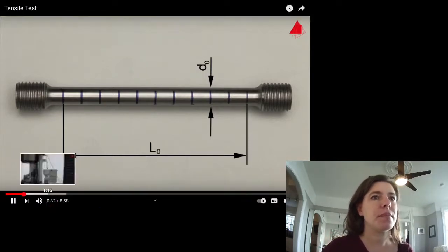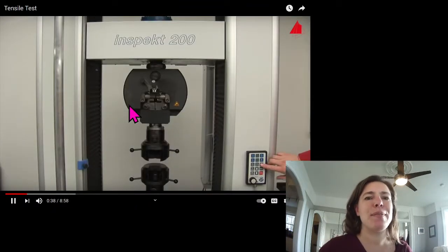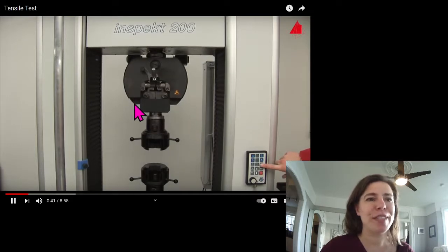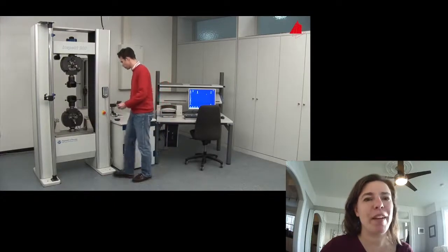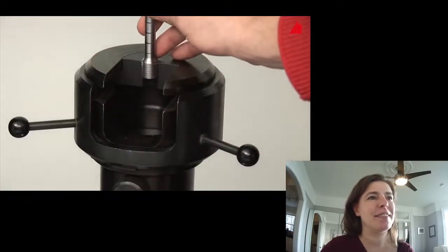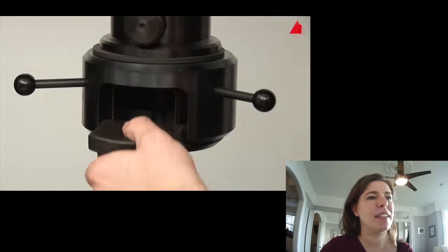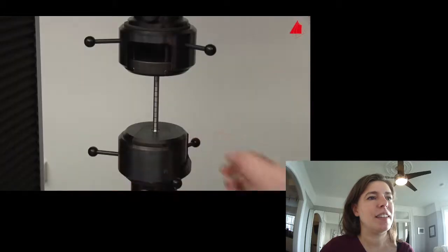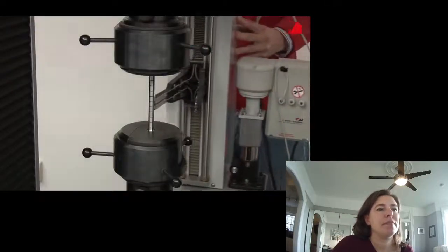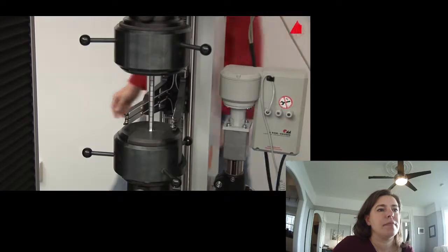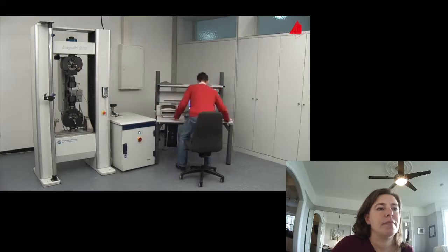They help to visualize and measure the plastic behavior of the specimen. They've marked it just to kind of help you measure. Using hand control, the tester moves the upper crosshead into its correct starting position. Now he can place the threaded ends of the test piece in the lower and upper grips of the testing machine. In the next step, he swings the extensometer into its working position and checks that everything is correctly prepared. Then he selects all necessary testing parameters on the control computer.